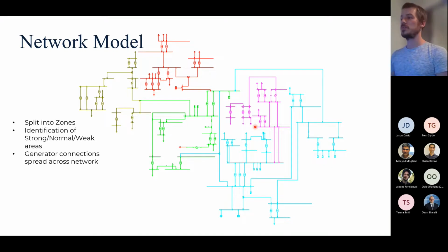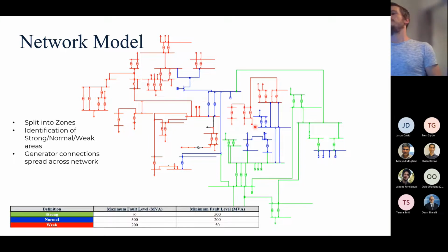It's anticipated to ultimately connect to a renewable energy zone. So we can expect a lot of renewable energy to be connecting throughout this network. The colors you see there are different zones that we split it up into. And ultimately it was a matter of connecting just as much generation as we could, or harmonic sources really is what we're talking about, connecting as many harmonic sources as we possibly could across the network and looking at how we actually mitigate the harmonic emissions. Again, taking that business as usual approach compared to actually just managing the harmonic impedance where there are actual issues.